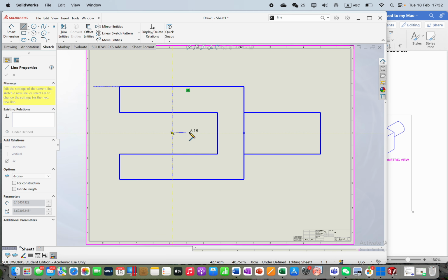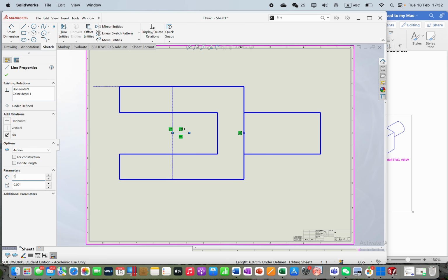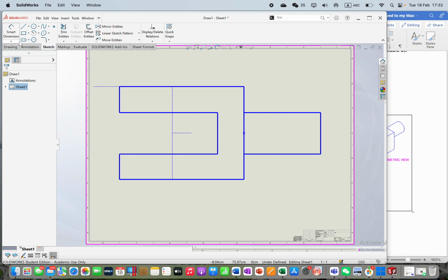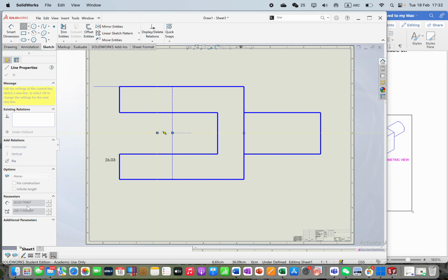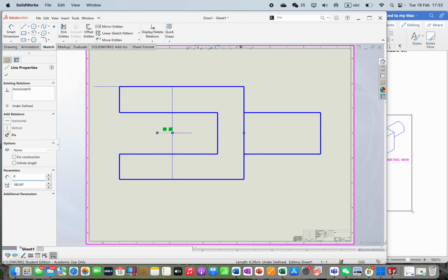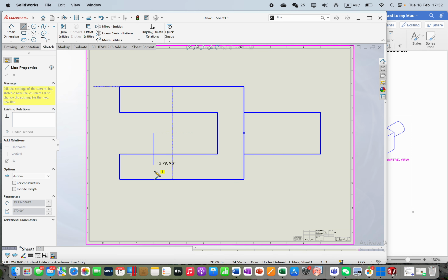We can just come here and find one of 8. This is just an example, right? You can do this in 1000 ways. So 8 centimeters to one side, 8 centimeters to the other, and I come here and I modify, and now we just simply create a line between these, then I will just trim it down.